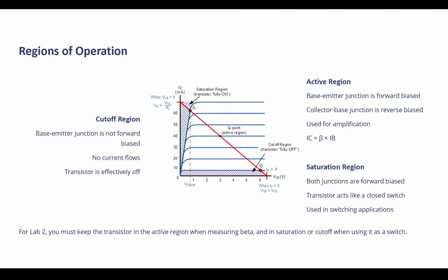That concept is one of the biggest differences between the two when it comes to controlling those transistors: in MOSFET, your control signal is voltage. In BJT, your control signal is current. So if you want to control a BJT, switch it on and off, or use it as an amplifier, we're going to talk about that in a minute, you have to tune the circuit or control the circuit using an injected current.